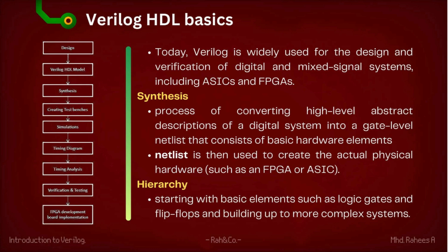Now Verilog is widely used for design and verification of digital and mixed signal systems, including both ASICs and FPGAs. It supports a range of levels of abstraction from structural to behavioral and is used for both simulation-based design and synthesis-based design. Synthesis in the context of hardware description languages is the process of converting high-level abstract descriptions of a digital system into a gate-level netlist that consists of basic hardware elements such as logic gates and flip-flops. This netlist is then used to create the actual physical hardware.